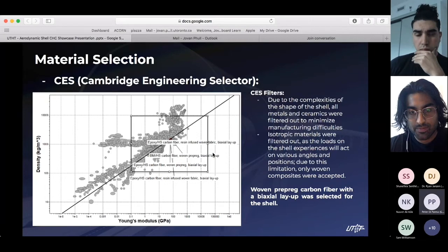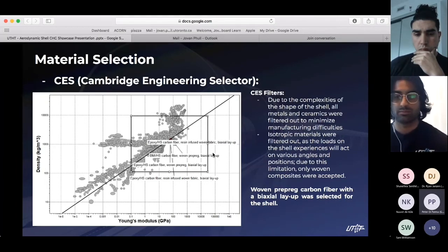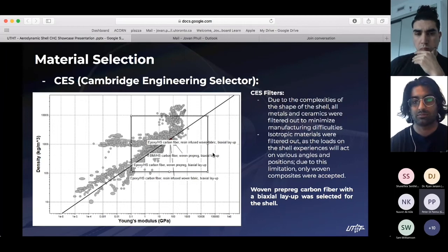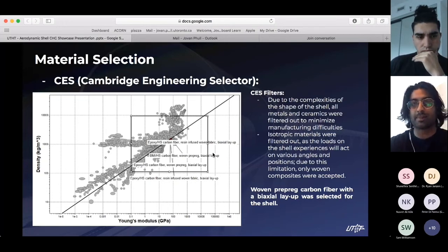So if you were to just not include it at all, what is the concern if you were to just lay up several sheets of carbon on their own rather than having the honeycomb in the mix? So you would need more layers. We only have 3 on each side, so that's 6 total layers. If we weren't to include the honeycomb, I don't know how many layers off the top of my head, but it would be more layers to achieve the same amount of performance. So adding in the honeycomb just increases the efficiency without increasing the density and also without increasing the cost too much.